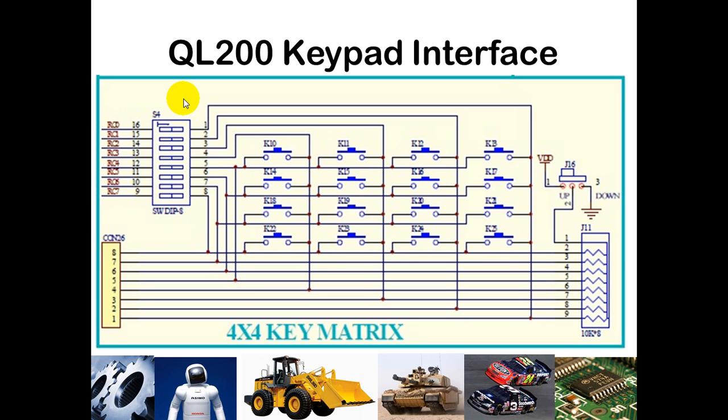And then you'll notice on here that each of our buttons in the keypad is simply a switch, a normally open switch, and when it is pressed, it closes. And so when that is pressed, what you'll notice is that there's a connection. So for example, if we press this, line 4 right here is connected through this, and then is connected on down right here, and is connected down to there.